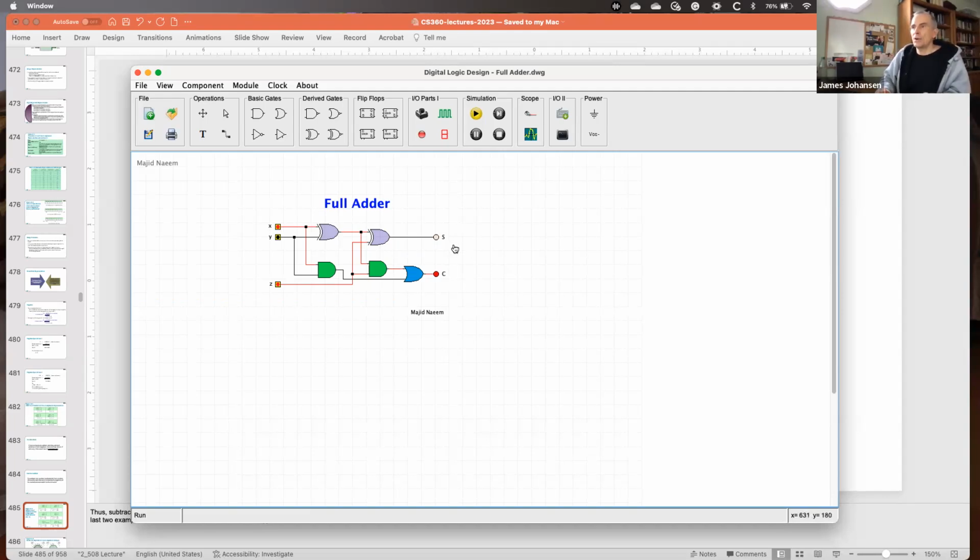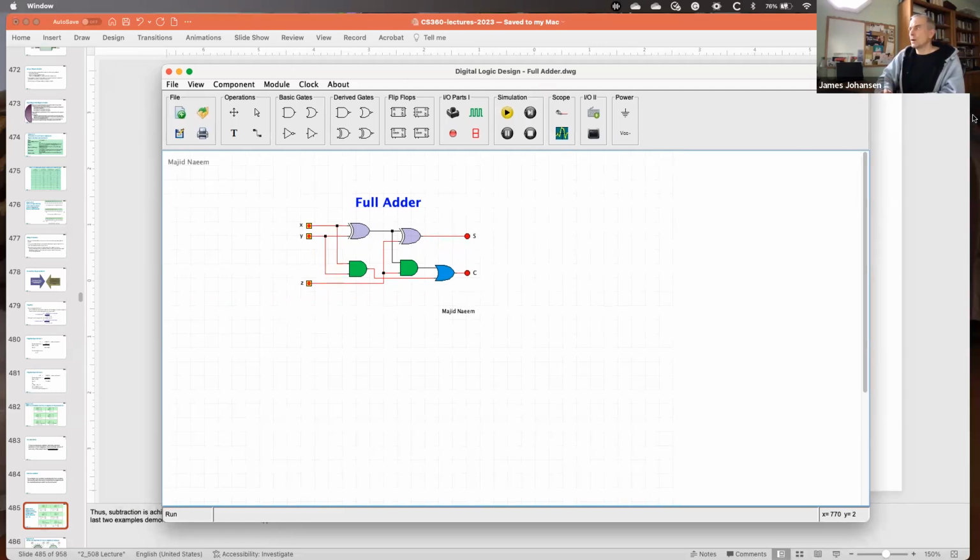And so I get a carryover, but not this particular element here. And then finally, we have the case where both of them are positive. The carry input is positive, and then you get a result of both of these lights being lit. So this is another reminder that everything we're doing, we think of the capability of an ALU, you can break it down into digital logic.